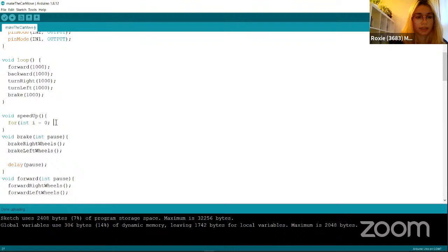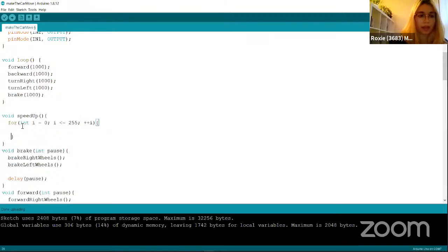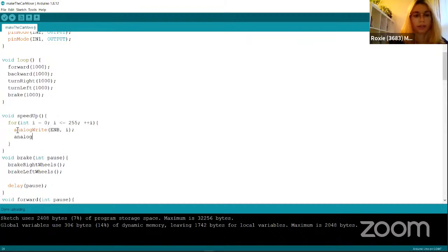So I'm just going to say speed up, you'll see in a second, i is less than or equal to 255, plus i. And here what we're going to do is we're going to say analogWrite ENA, i, and then analogWrite ENB, i.